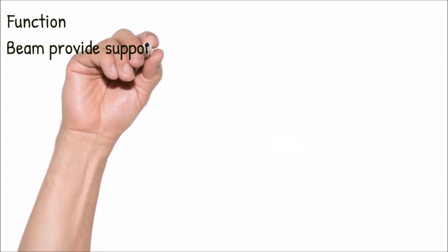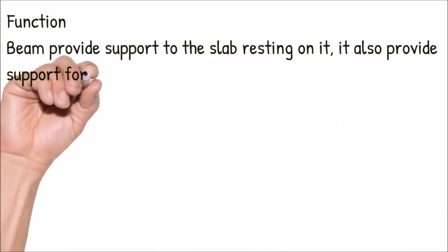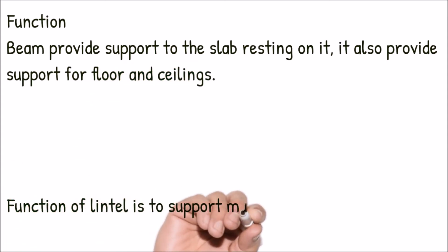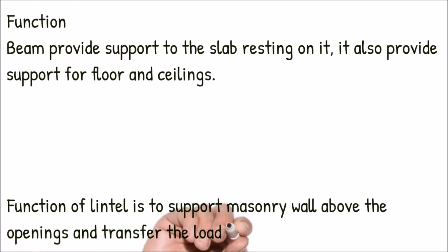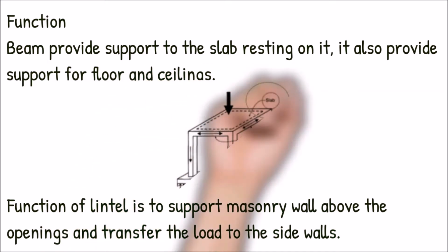Function: beam provides support to the slab resting on it. It also provides support for floors and ceilings. The function of lintel is to support the masonry wall above the openings and transfer the load to the side walls.